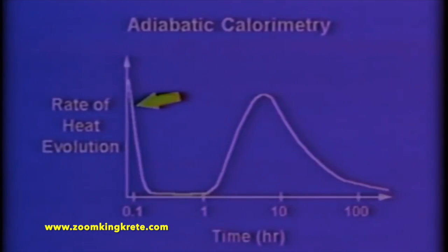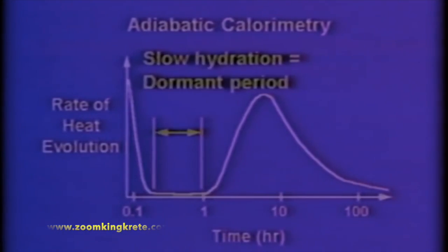After the initial dissolution, hydration products are quickly precipitated on the surface of each cement particle. The layer acts as a protective barrier and temporarily delays the further dissolution of the particle. This slows down the reaction for a period of several hours and is called the dormant period.